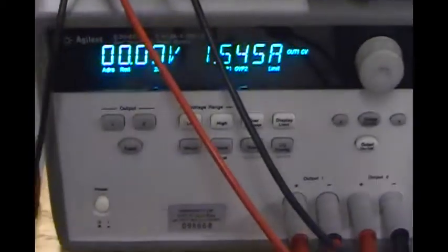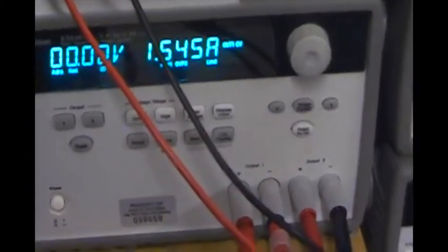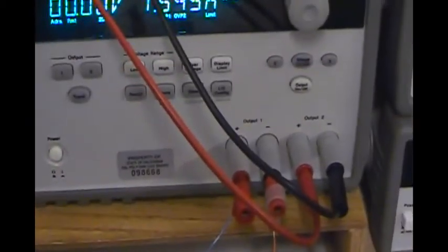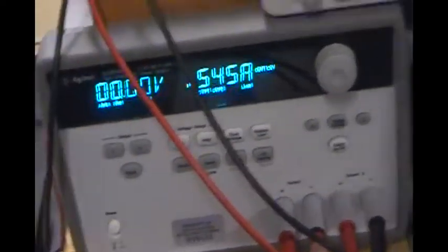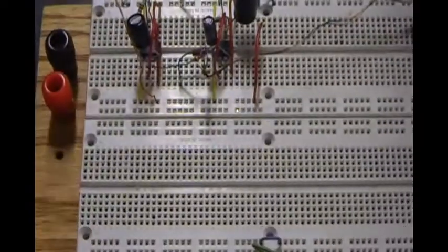So, what I did is I made a LabVIEW program that will play a song through the power supply here, because this is the only thing that will give us up to 20 volt output. A LabJack won't do that, so we had to download a program right here, this little LabVIEW VI, that allows us to connect the computer directly to the power supply and output whatever voltage we want to our circuit, which is going to allow us to play a tune.